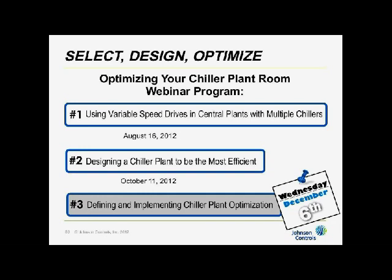Because for a cooling coil, typically a spray cleaning method is used, and you can only spray about 4 rows deep. And most engineers have at least 6 rows for cooling coils, so you've got to be able to get to both sides. The typical answer to that, of course, is you've got a coil pull, and that's always provided to get the coil out, and then you could clean it. But now you've got to disconnect all the piping and everything else. So if there is not an issue of budget and there's not an issue of space, then put an access section on both sides and make it easier to clean the coil.